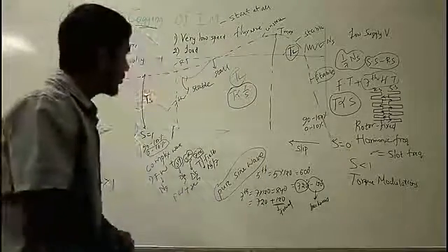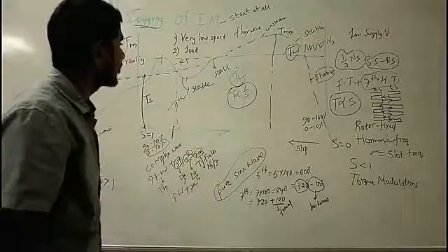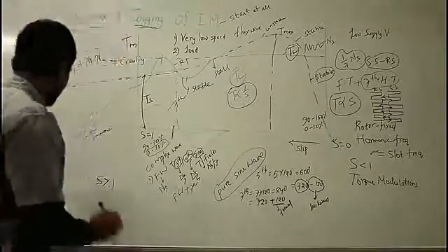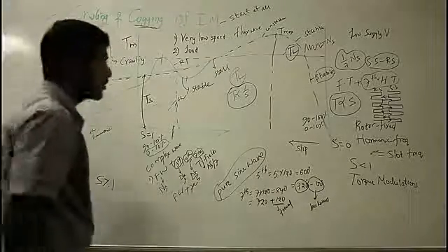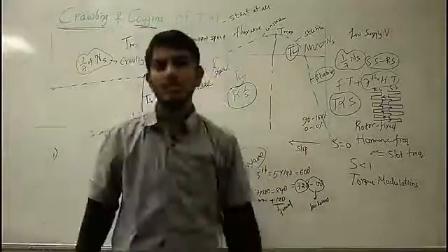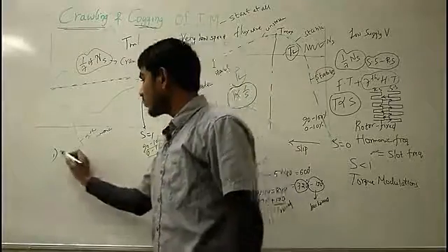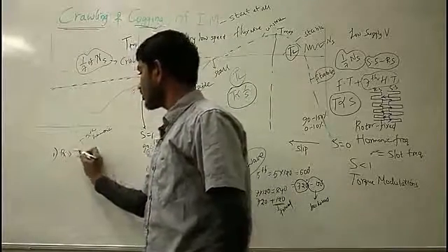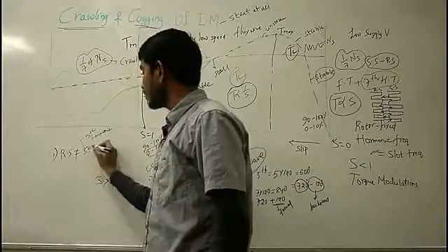Now let us see the remedy to overcome the cogging effect of your induction motor. The first remedy is you have to ensure that the number of slots of your rotor should not be equal in number with the stator slots. That means they should not be equal.